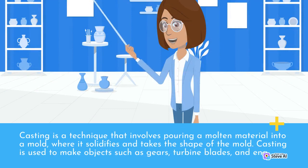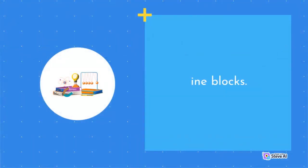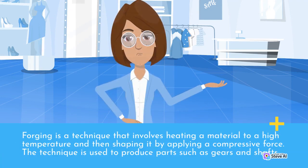Casting is a technique that involves pouring a molten material into a mold, where it solidifies and takes the shape of the mold. Casting is used to make objects such as gears, turbine blades, and engine blocks. Forging is a technique that involves heating a material to a high temperature and then shaping it by applying a compressive force. The technique is used to produce parts such as gears and shafts.